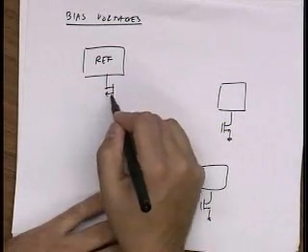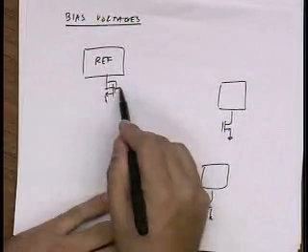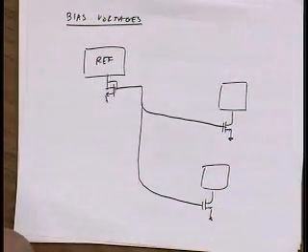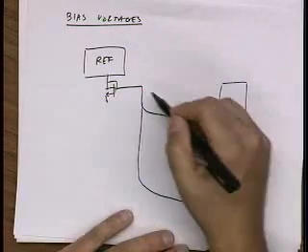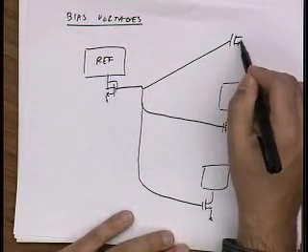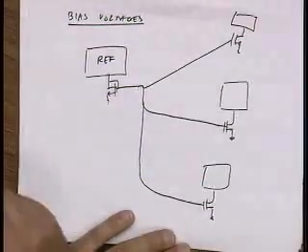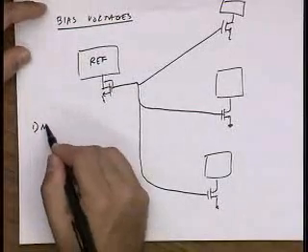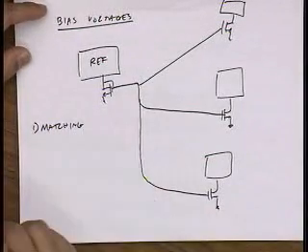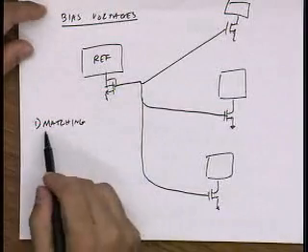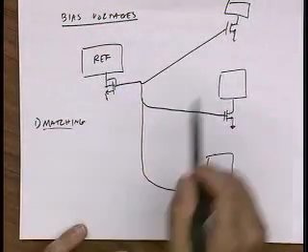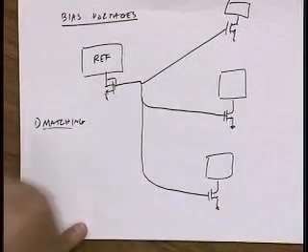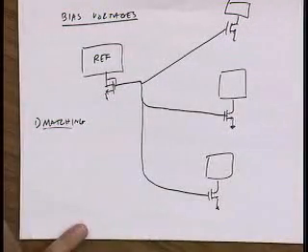So here somewhere there's a diode connected device, right? And I basically route like this, in order to route currents to different parts of the circuit. Okay. Now, we've already discussed some issues with this. One is matching. And in fact, this is probably one of the biggest reasons why we don't want to do this. Because these transistors are physically far away, their threshold voltages are going to have a mismatch, and there's going to be a big problem.